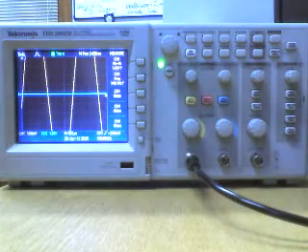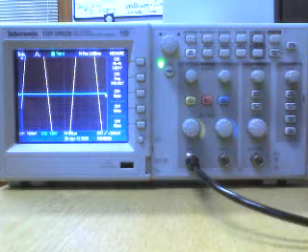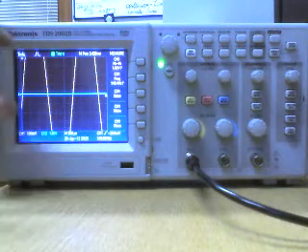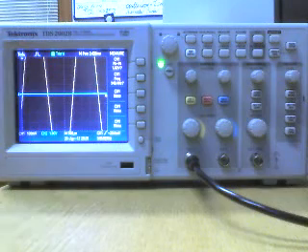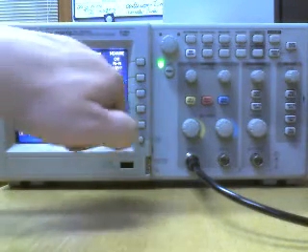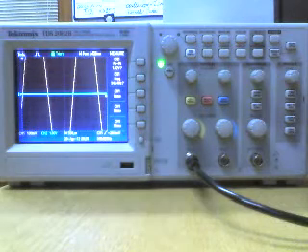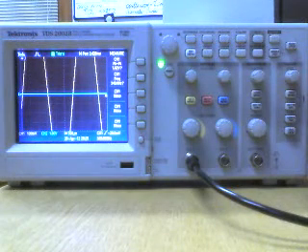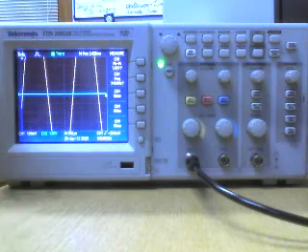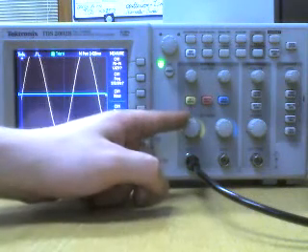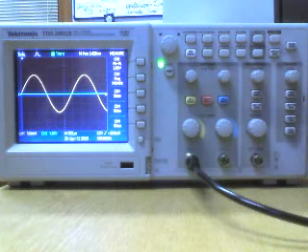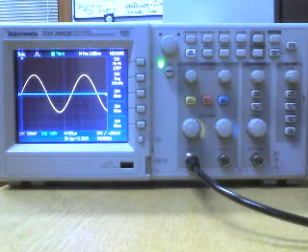And the greater the volts per division, it's at 100 millivolts per division now, the waveform is completely off the screen. It's only able to measure 1 volt, and it gives you a hint that it's got a problem because it's got a question mark next to the number. So if you're using the measure function, keep the voltage on the screen as big as it can go, and you'll get a nice accurate number.